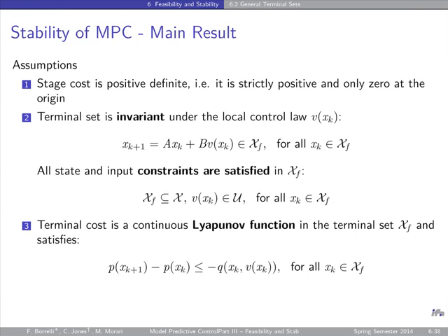Okay? This is again something which is hidden, but it's very important. You don't have to tell MPC there exists a v, which v is it? Okay? You need to know that in xf there exists a v. MPC will find it for you because it looks among all possible feasible sequences and therefore all possible feedback laws, and you will find one that keeps you in there if there exists one. Okay? The second thing you have to do, you have to design this p, which is a Lyapunov function, and that's this decrease. So you have to do another piece of software that will give you this expression of p. Maybe you're looking for a quadratic function, so we'll give you the p matrix. And you have to use the p matrix as a terminal cost and xf as a terminal constraint. And if you satisfy 1, 2, and 3, you will have persistent feasibility and asymptotic stability.